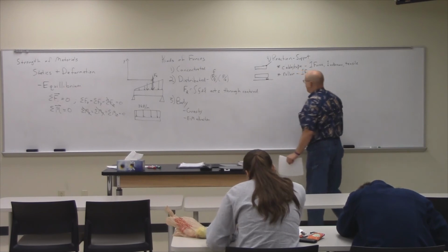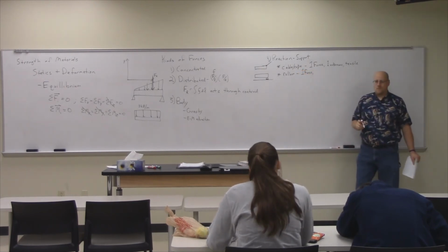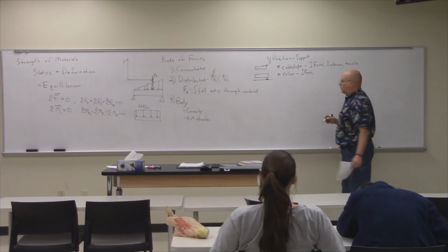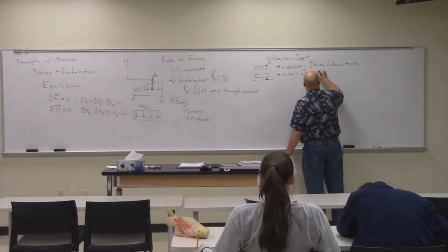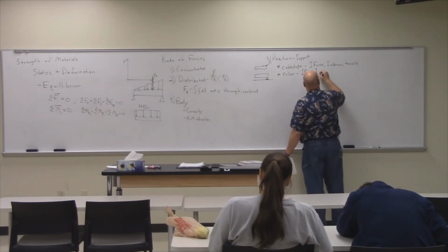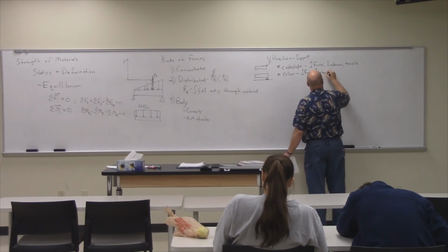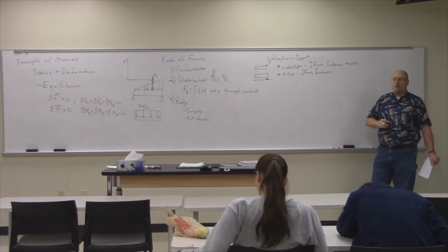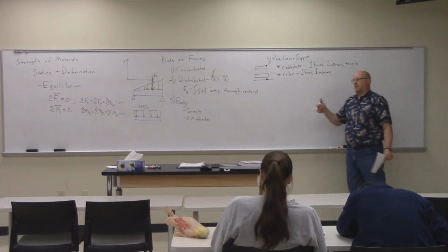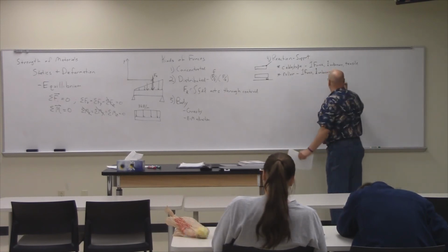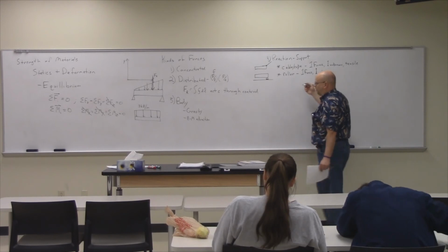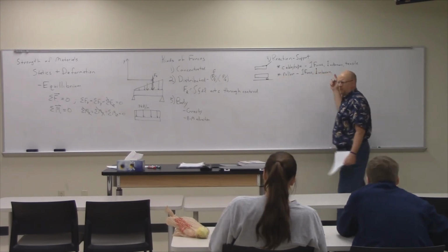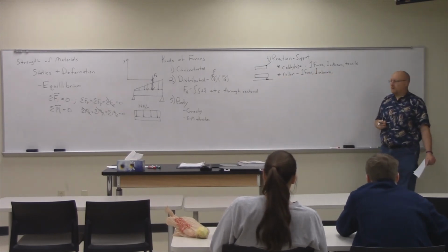Do we know its direction? Right, it's perpendicular to the surface on which the roller is rolling. So we are left, therefore, with just the one unknown. And we know that the force has to be up. It's not attractive. So again, it's just up. Tensile or compressive doesn't really mean as much in this configuration.